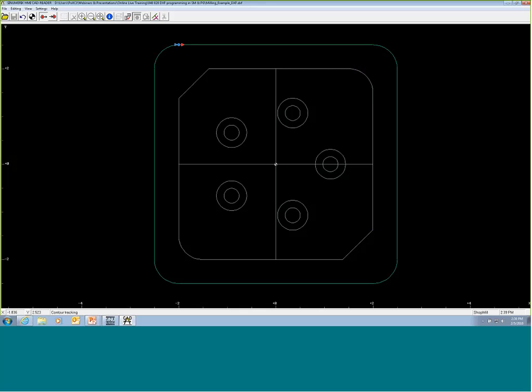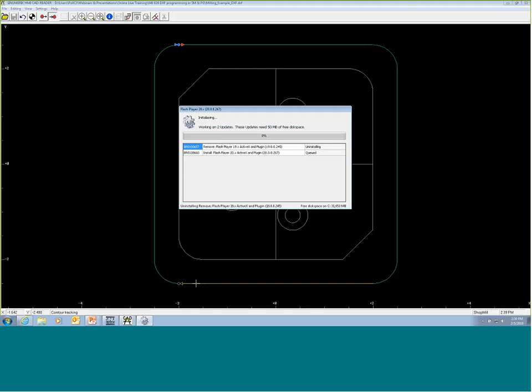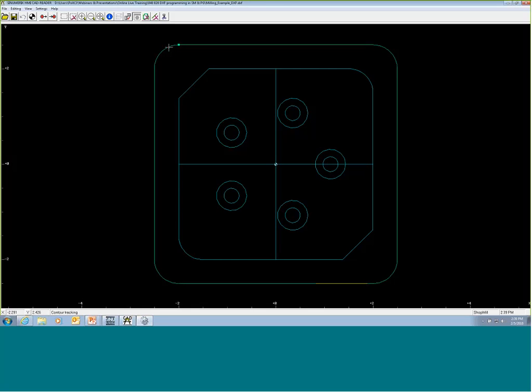Now you see how since everything intersected, there weren't any scenarios where it was questioning which direction you want to go because something was maybe what it thought was intersecting. It will automatically chain the whole feature. Now, you're not tied into picking the whole feature, however. What you do is the next step would be you pick the endpoint, and you have the same kind of options as you had in the beginning. So I can pick an element endpoint, but now I can pick which line I want to stop at. So if I only want a half of it, I can go in and pick half of it. If I want the whole thing, go back to the last arc, click it, and now the whole entire feature will chain. So once I have it all green, that means that that contour has been selected.